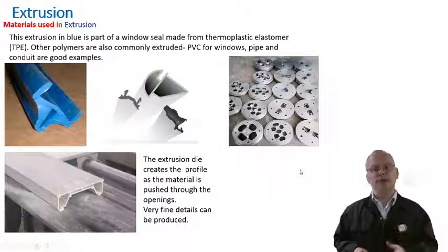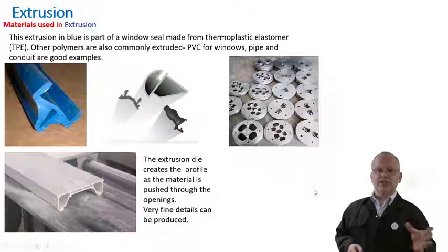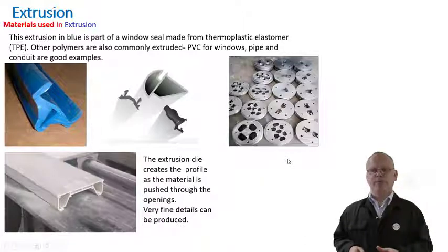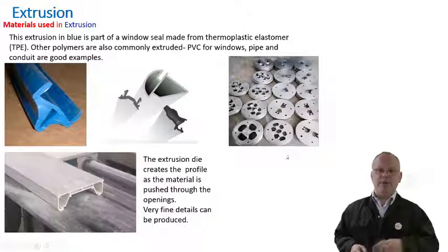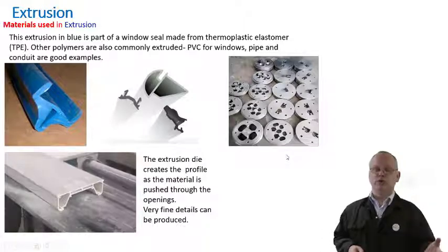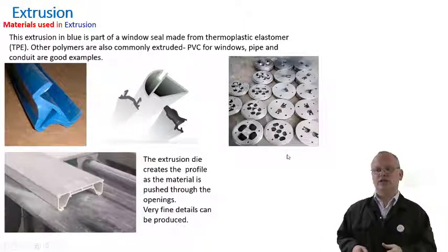Extrusion is also used with aluminium. You wouldn't use the same machine to do it because the temperatures would be so different and the pressures would be so different, but in principle aluminium is an extrusion suitable material in the same way as polymers are. So the machine is not far different in the sense that that die is what gives them their profile. Okay, extrusion.